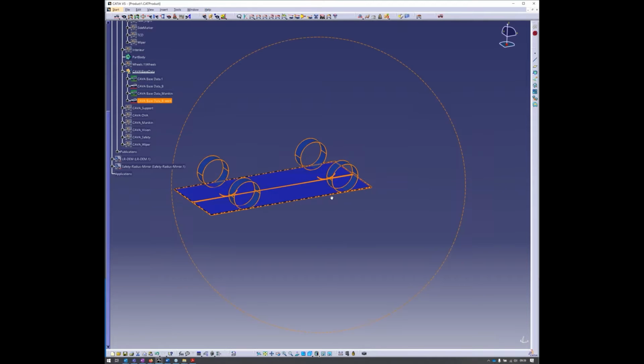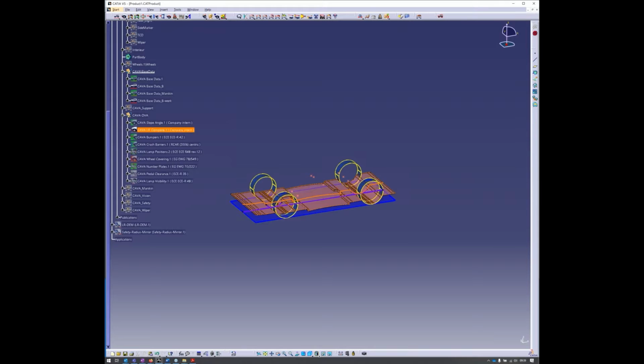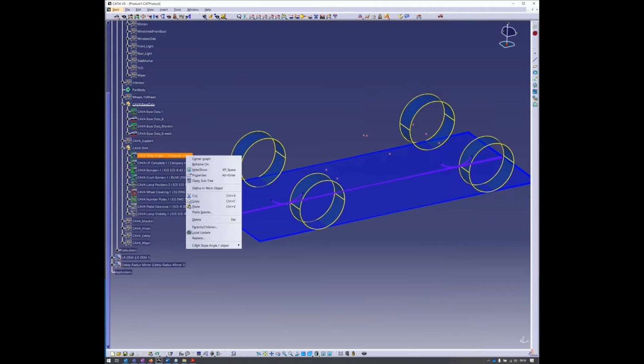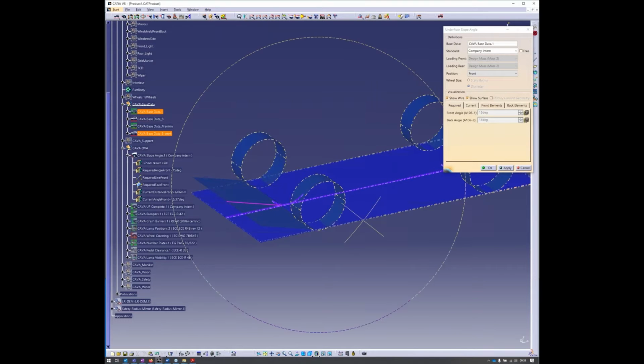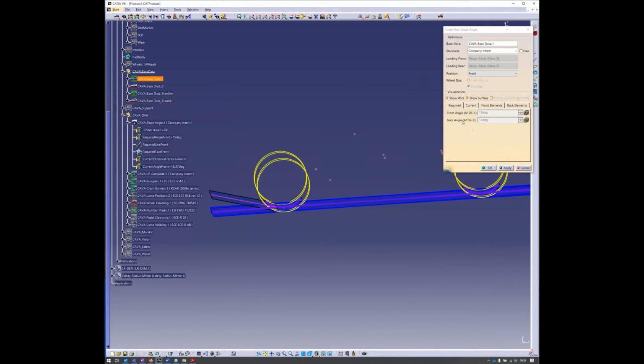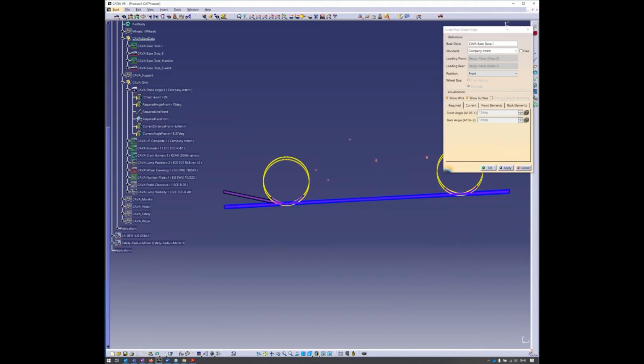Okay, when you have this information, you can already start doing some CAVA work, like start with, for example, the underfloor analysis, because this is mainly based on your wheel positions and the road plane. So you could, for example, already show the requirements for the slope angle achievement. If you're having some requirements about the slope angle and you want to achieve a certain front angle, CAVA will show you, without having any car geometry, already the boundary surfaces of where you can have clear space to your geometry.